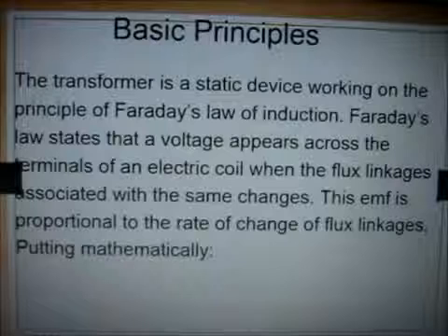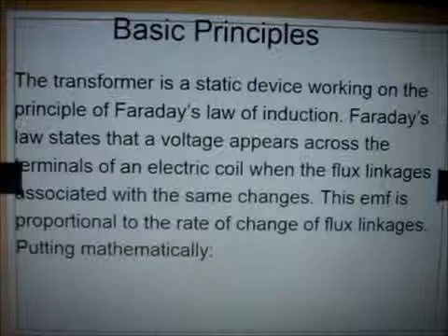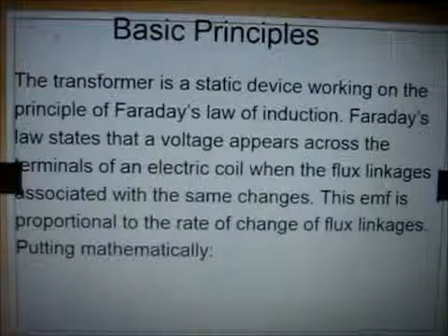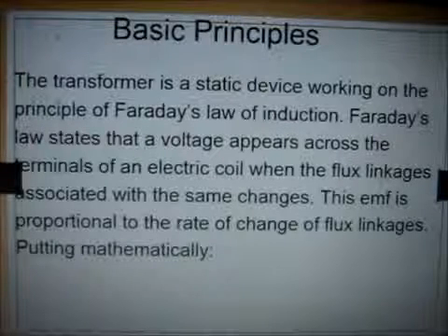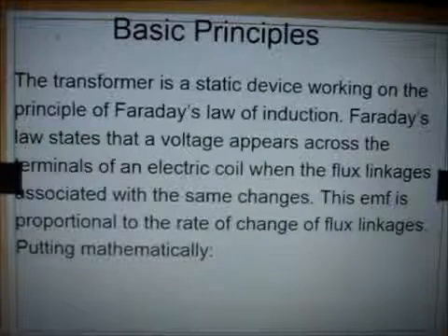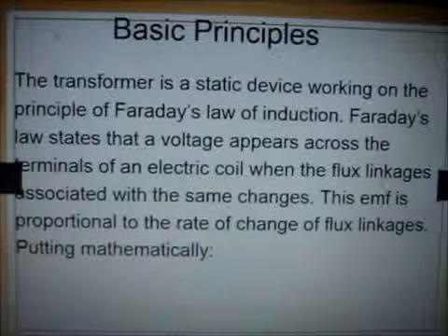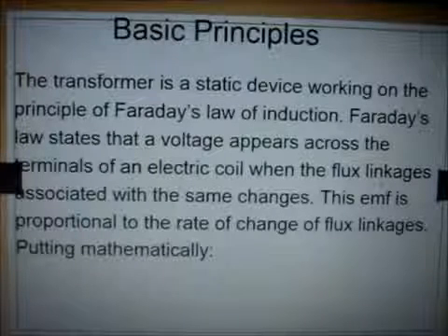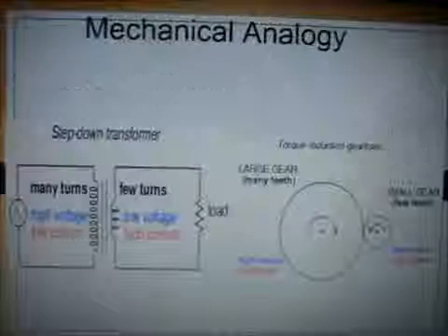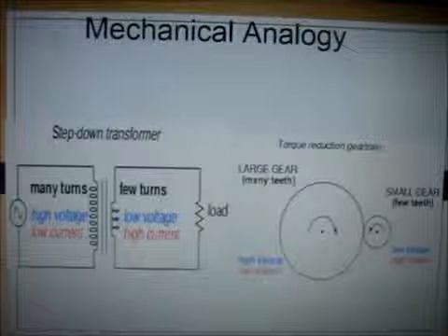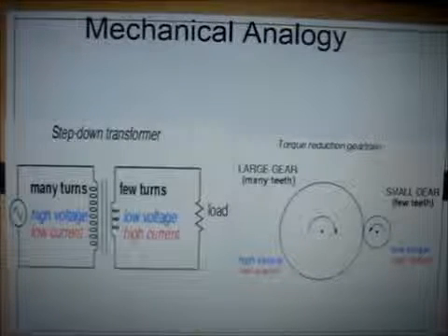Now, the basic principle behind a transformer. As said before, the transformer is a static device working on Faraday's law of induction. Faraday's law states that a voltage appears across the terminals of an electrical coil when the flux linkage associated with it changes. This EMF is proportional to the rate of change of flux linkages. So whenever there is a rate of change of flux linkage, we get an induced EMF, and that is what happens in the case of a transformer. Mathematically, we can get the EMF equation as minus d phi by dt, and the minus sign is given by Lenz's law.